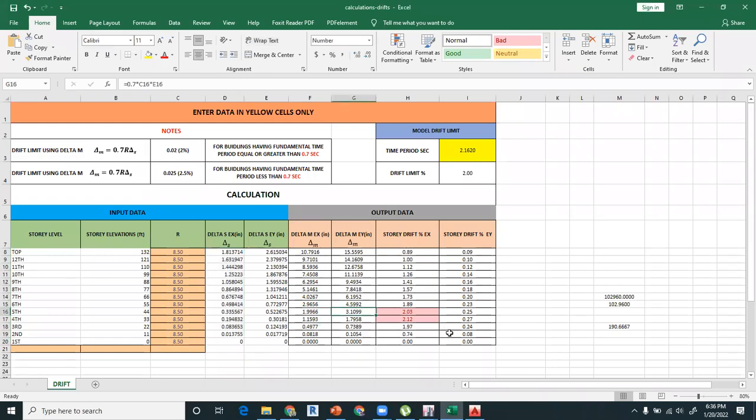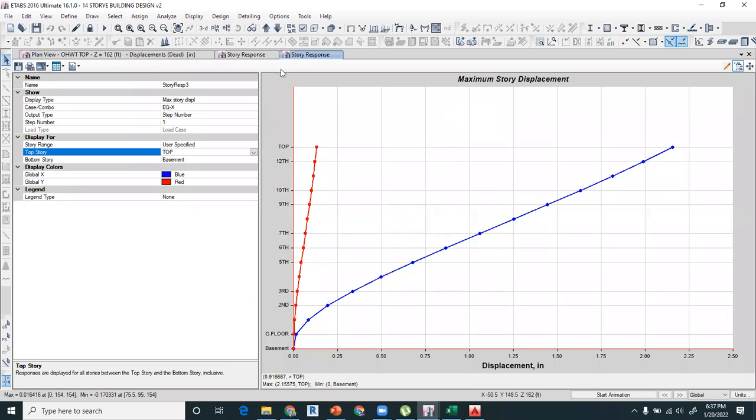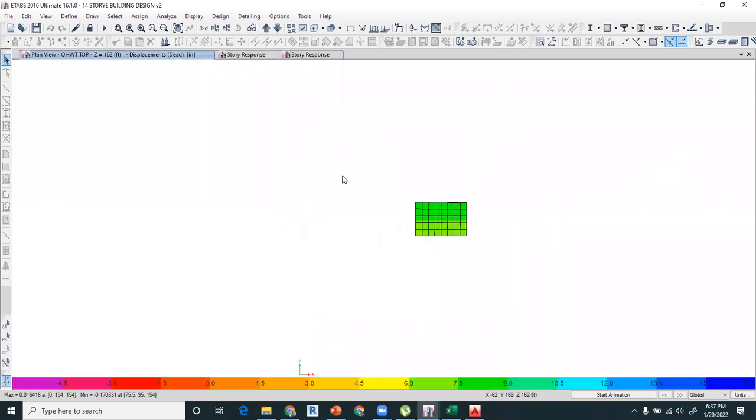So now again there is an issue in the lower stories, that the drift is not controlled by these 4 walls, so you have to give another wall or maybe 2 in order to control this drift. So it is in the 4th and 5th story, right? So again you have to go to the ETABS.